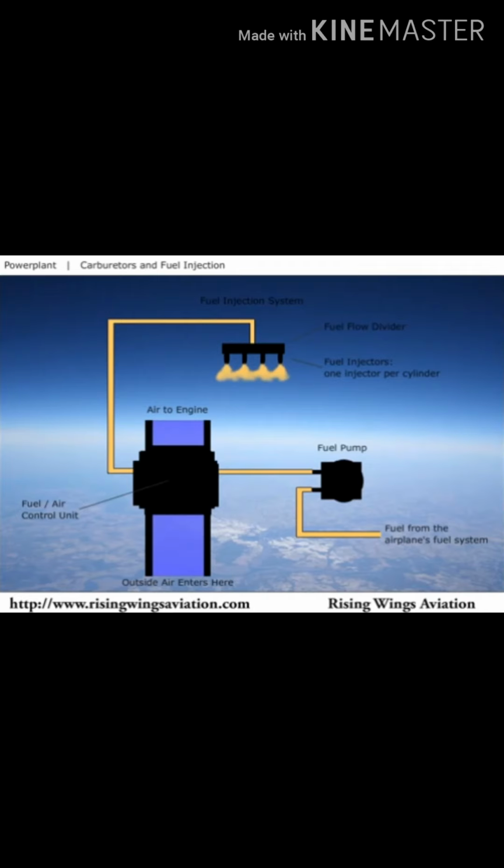Each cylinder has its own fuel injector, which vaporizes the fuel just prior to the cylinder's intake valve. Since there is no venturi, a fuel injection system is less susceptible to internal icing. The high temperature of the cylinder makes ice not likely to develop at the fuel injector either.